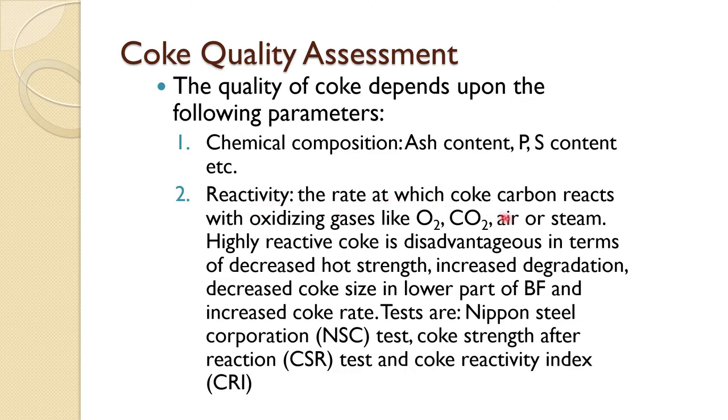Reactivity of the coke: the rate at which coke carbon reacts with oxidizing gases like oxygen, CO2, air or steam. So, really we do not need a very highly reactive coke. If highly reactive coke is there, then it has to travel from the top, from the throat to the tuyere level, and if it is highly reactive, by the time it reaches the tuyere level, it may not have sufficient strength and the permeability or porosity to withstand that and give a proper passage for the gases to escape.